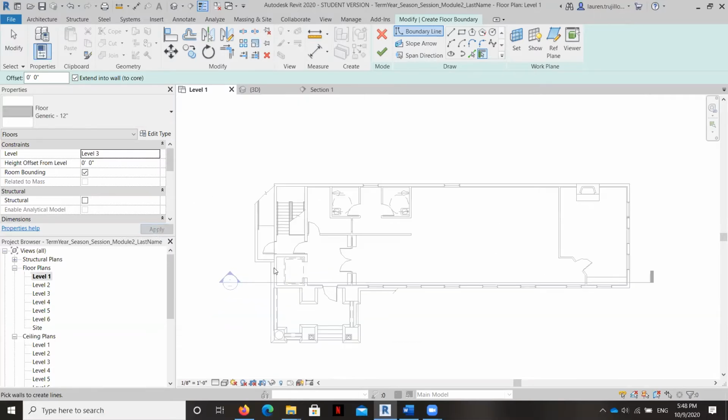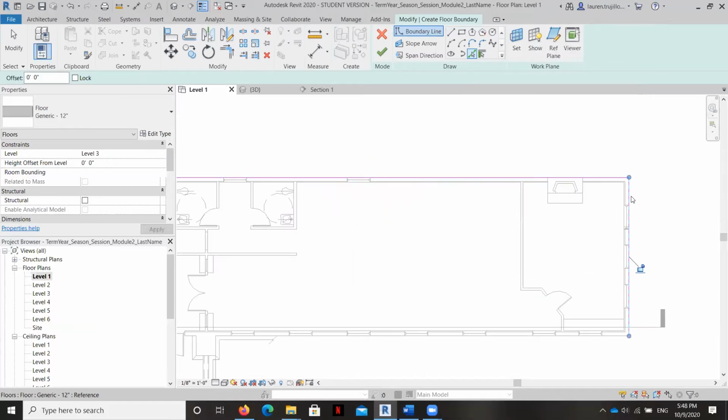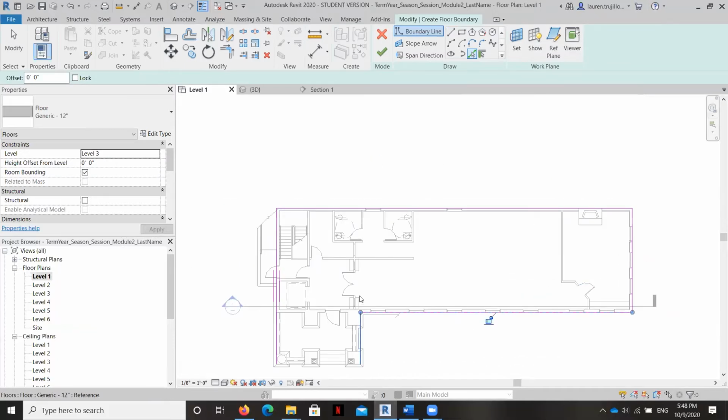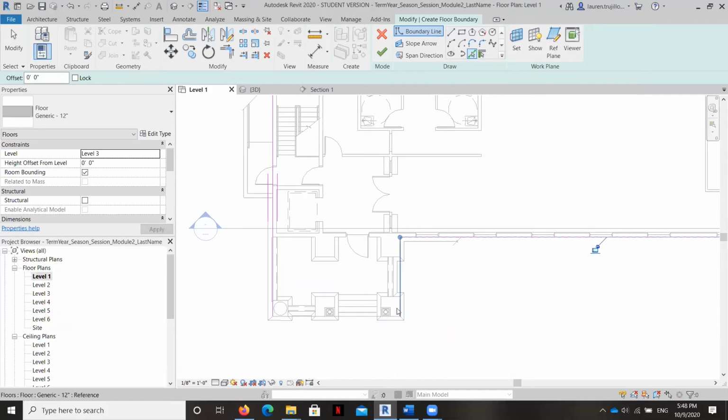And then what I'm going to do is see if it's going to let me pick lines. And so in order to do that, I'm going to see if it'll let me just grab the lines. And this is a way to make some of your drawing go quicker. Instead of drawing the outline on the floor like we did with the first one, I'm going to go ahead and just pick lines. See if it'll let me. Yeah, it'll let me. Okay. So now instead of drawing, I can grab existing geometry or existing line work. What's going to make Revit just a little bit mad is if I don't grab the right lines or if they intersect at any point, but these should be good to go.